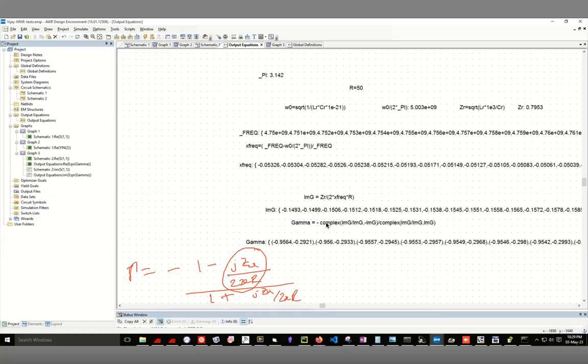But I have to define it as a complex number. So in Microwave Office, that function is basically this complex. In brackets, you write down the real and imaginary part. Okay. So the real part is 1, but 1 is not an array. So I just divided img by img here to create an array of ones. And then comma minus img because of this minus sign here.